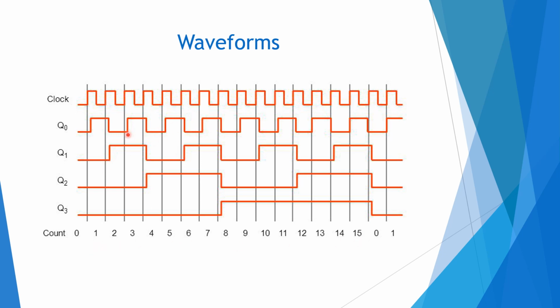Again, we can see the waveforms here. At the LSB it is half of the clock, and at Q1 it will be 1 by 4, and here 1 by 8, and finally 1 by 16.